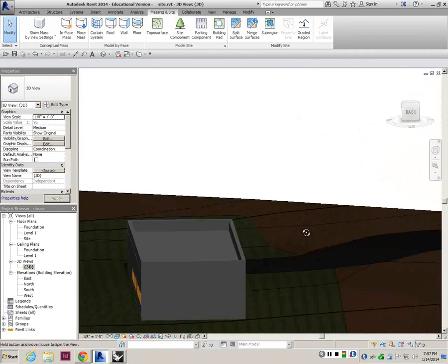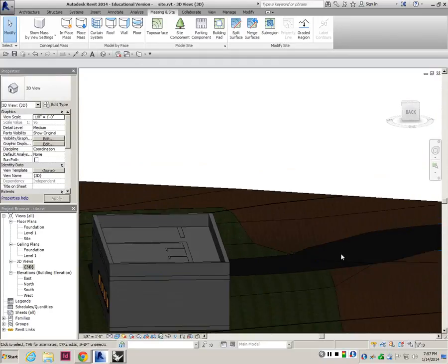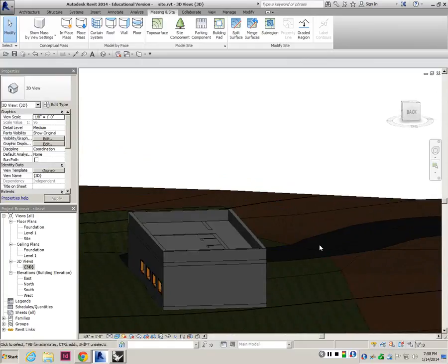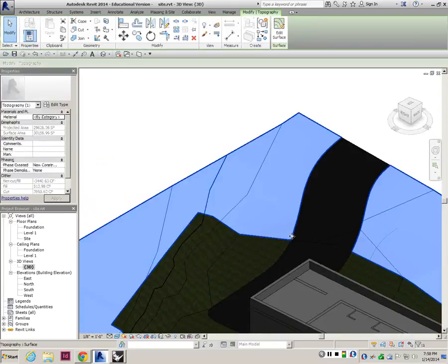And you can also further do detailing on the road, but this is kind of outside of our property line. But normally your topo lines would actually accommodate the road lines, like they would be perpendicular to the road, so that you would know the road slope is consistent on both sides. In this case, since I didn't adjust the topography here, this side is a bit more elevated than that side, but that should be okay.